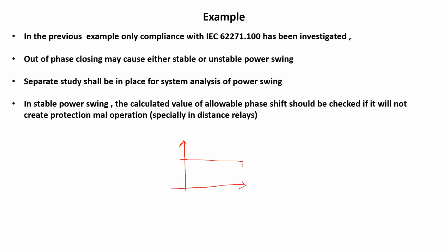Let's say we have this zone. What it sees is that the power swing is a reduction of the impedance, and if it's a stable power swing in and out, then if it has power swing blocking, it understands that. But sometimes it doesn't have power swing blocking. It sees it as a fault, so it will operate.